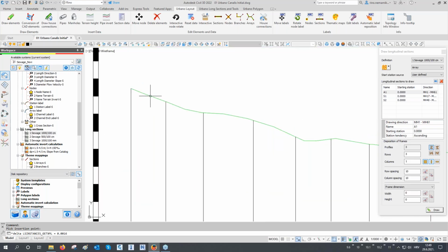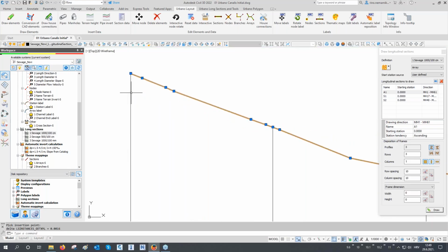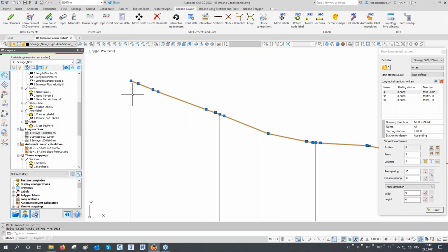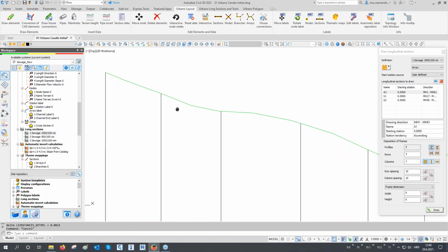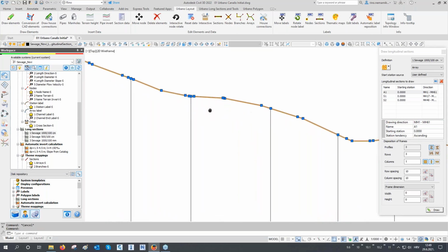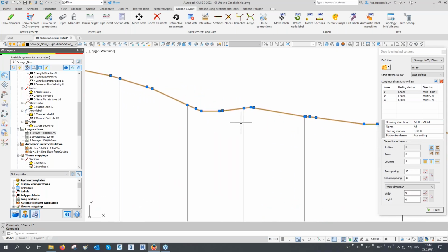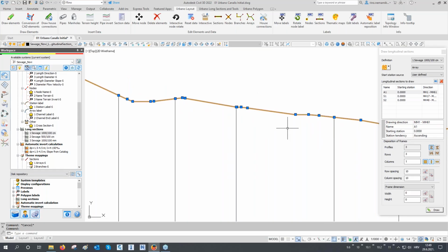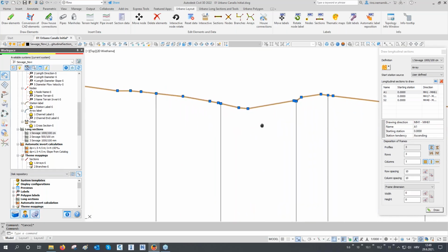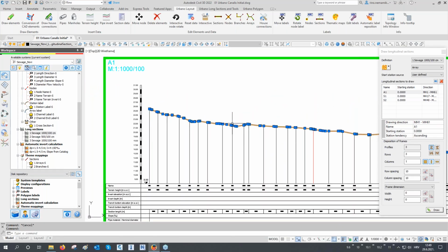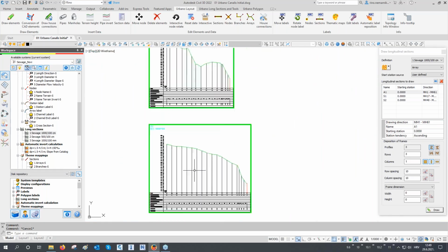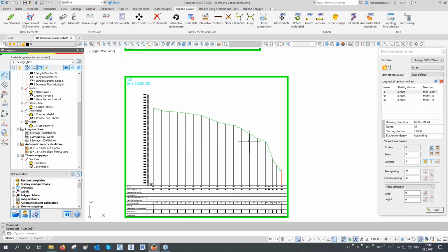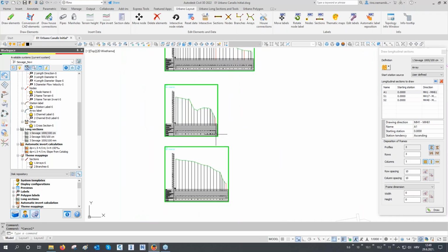And now if I pick on this green polyline, now we can see what are those additional points that I showed you. When we click draw additional points, these points are basically calculated. So everywhere where the section is crossing the DTM triangle, the software also took this elevation on that position. So we get this much more detailed terrain line, which is really, really important, especially afterwards if we would like to calculate the excavation volumes.